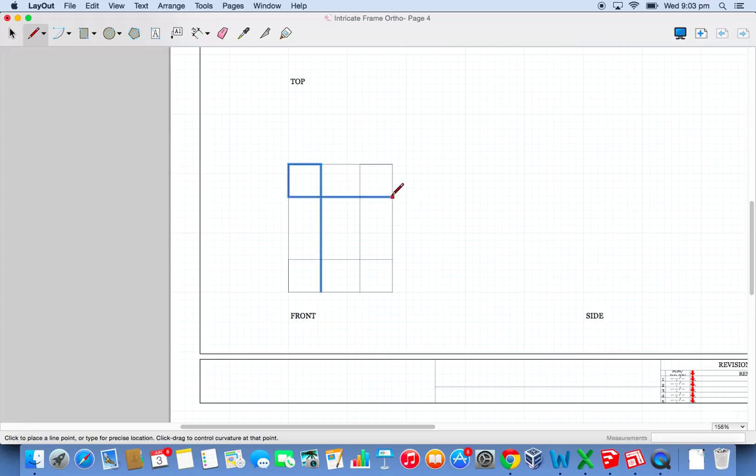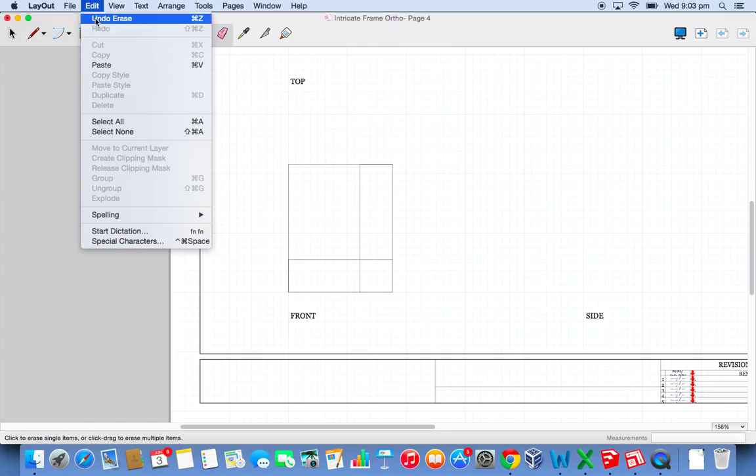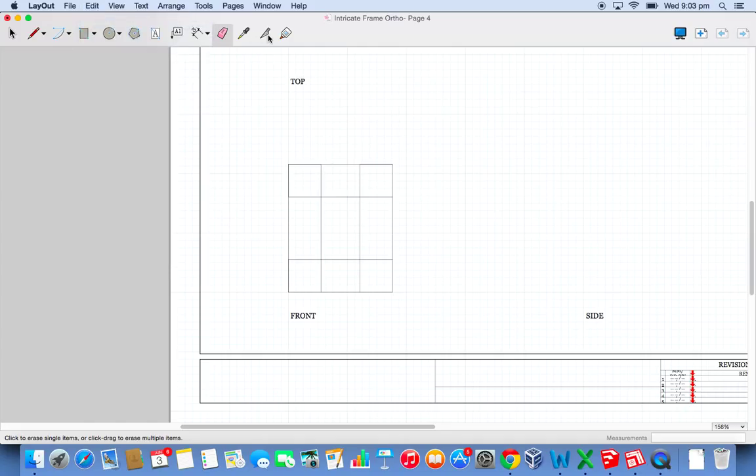Okay. Now, if we go and try and delete the lines that we don't need, it deletes lots of the lines selected. So I've worked out a way to get around that. It's this tool here. It's called a split tool. It's like a little scalpel, I guess, or a Stanley knife. So you pick up that and you draw exactly on the line that you want to remove.